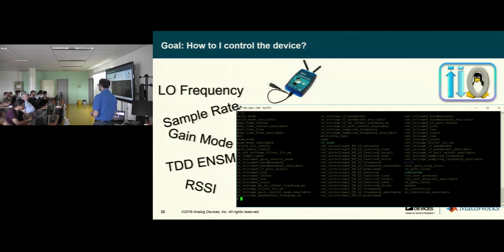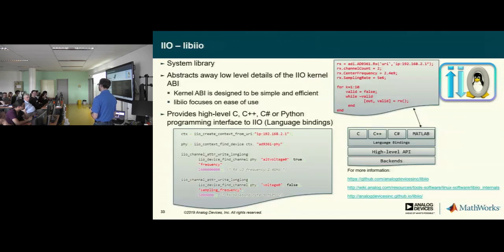You just mentioned setting gain. What kind of loop bandwidth would be unachievable if you do automatic gain control using a bash script? Or is this... It's not the recommended way, I think. Right. So if you have very tight tolerances on timing, you need to do things on the FPGA. Okay. Right.